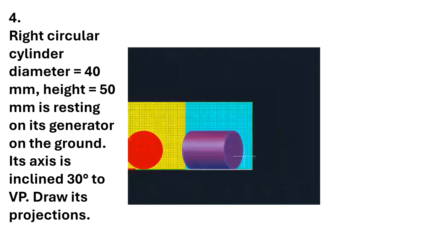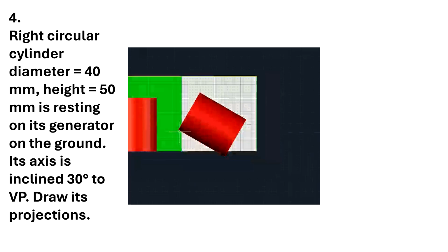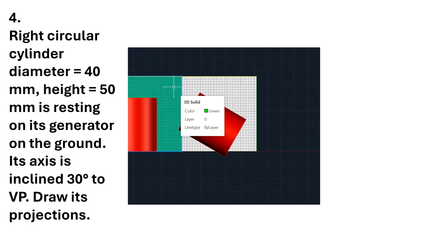The final front view will look like this. Here this base we can see, the other base, half of the things we can see. So how to locate the hidden lines? The hidden lines we will easily locate from the other view. From the other view, you draw a line joining the leftmost corner to the rightmost corner. Whatever is below, all of that will be visible, because we are seeing the front view from this side, and the other side of the corners or edges will not be visible. Accordingly, we can assume and identify the hidden lines.